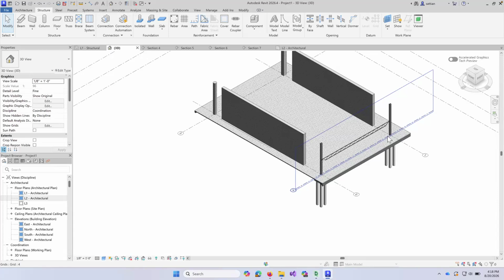Well, we could do that when we have these diagonal members. So when wind hits the side of the building, this diagonal member goes from top to bottom, and it will convey that force to the bottom. A lot of times you'll see X braces. Those X braces are to say, if wind hits from this side, this will take the load. If wind hits from that side, the other side will take the load. Right? So that's the purpose of braces.